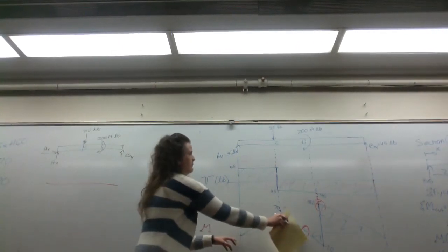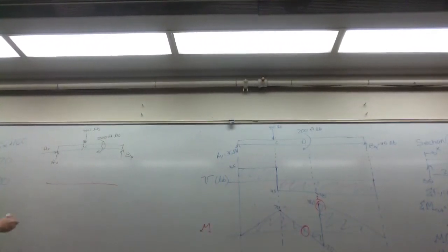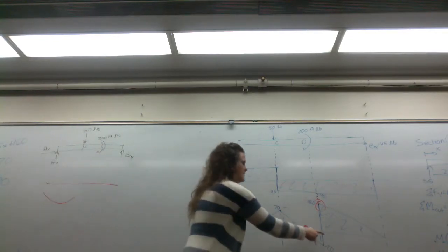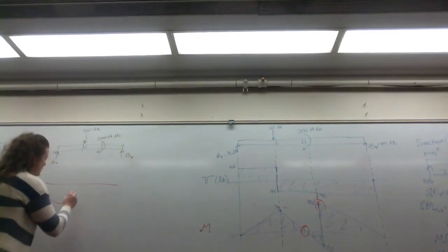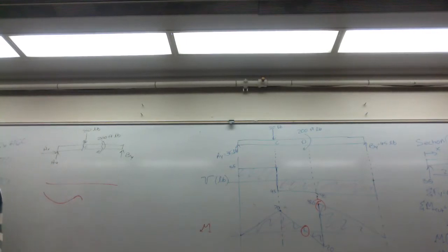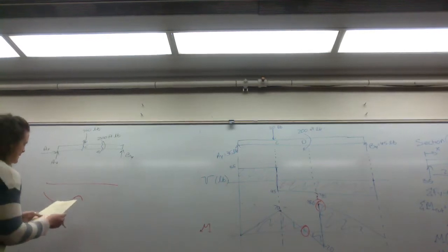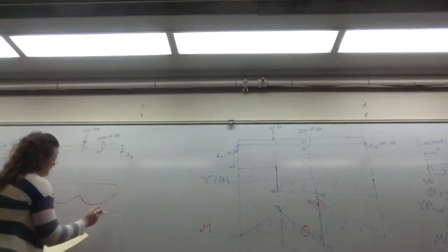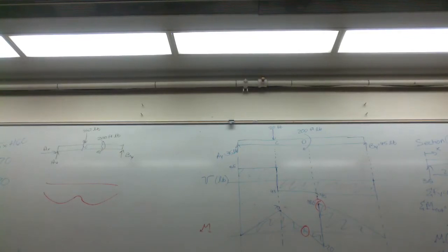So from A to between C and D, we're bent concave up. Then we have a slight bit of a negative bending moment, in which the deflection of your beam is actually concave down. And then we're positive again. So we're bent concave up. This is very much exaggerated. But we can see the deflection. And see that as that inflection changes, that's the failure point.